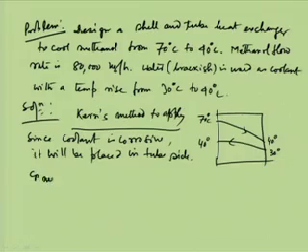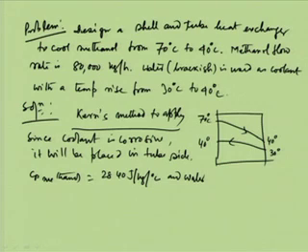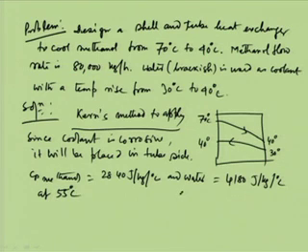Now, Cp of methanol is equal to 2840 joule per kg per degree centigrade, and water 4180 joule per kg per degree centigrade. This Cp of methanol is at (40 plus 70) by 2, say 55 degree centigrade, and water at 35 degree centigrade, the average temperatures.